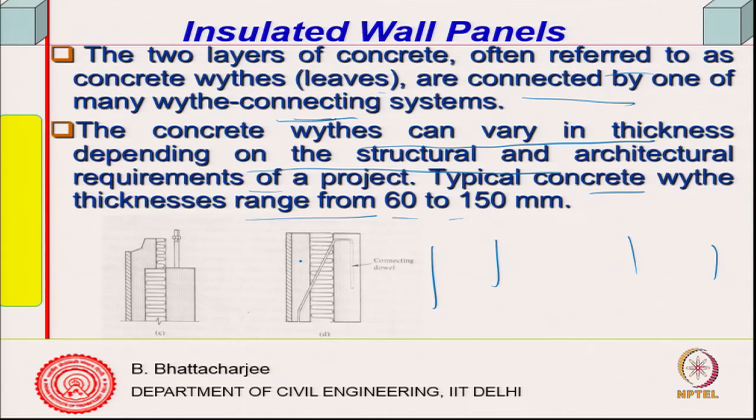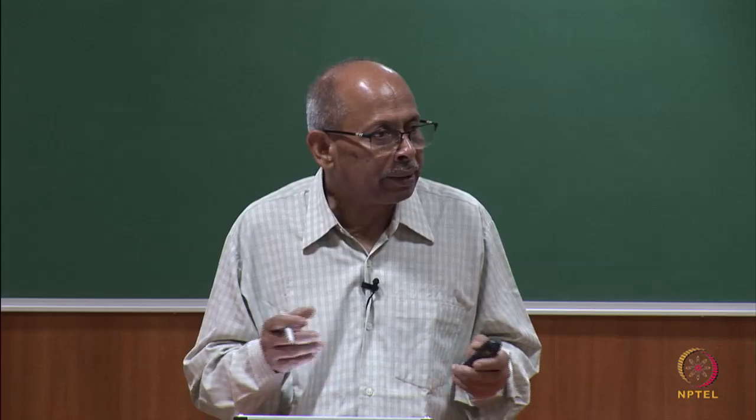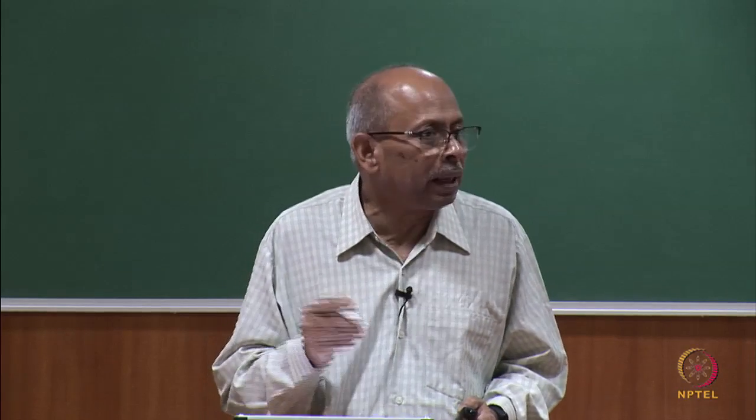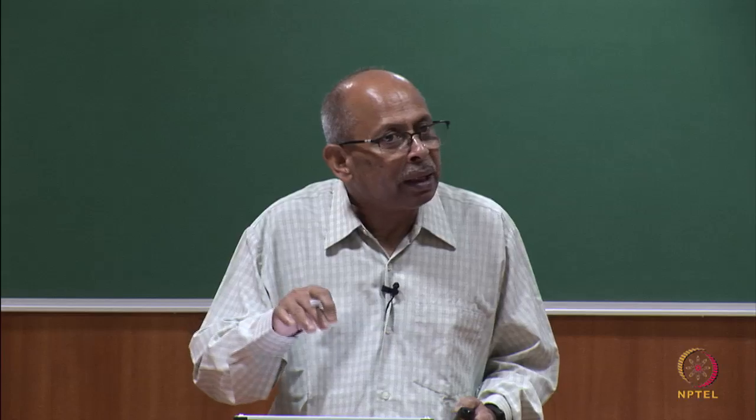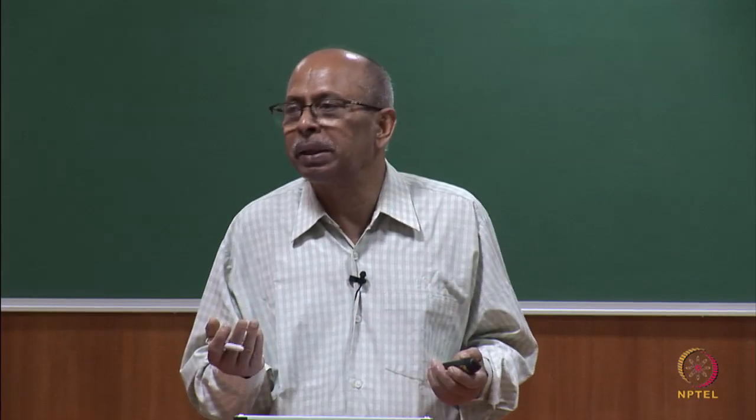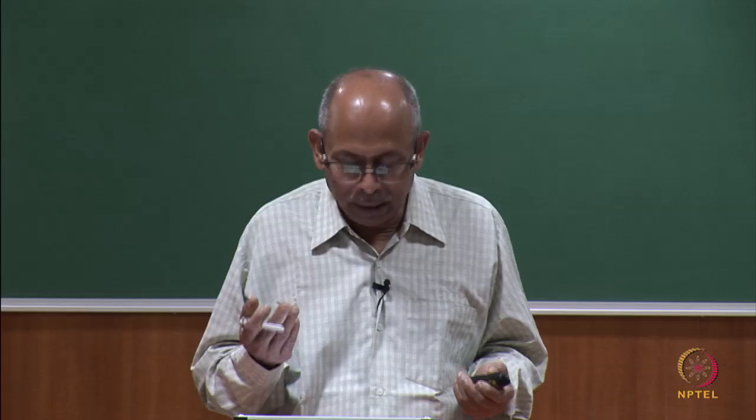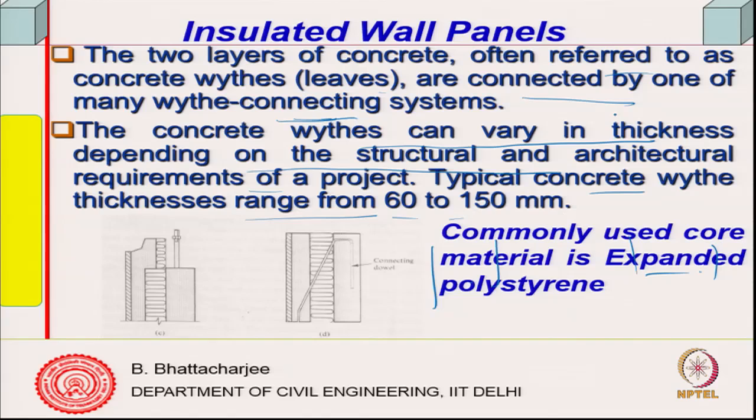So, the thickness of this one will depend upon the flexural load carrying capacity, because they are the ones which carry the flexural load, as I showed through the stress block. So, the concrete carries the flexural load, the shear transfer takes place through the core, which also acts as an insulation. So, it is a multifunctional system and can use expanded polystyrene or polyurethane foam. This is thermocol, as you know, something of a similar kind you can have, and this is what makes it a multifunctional system.